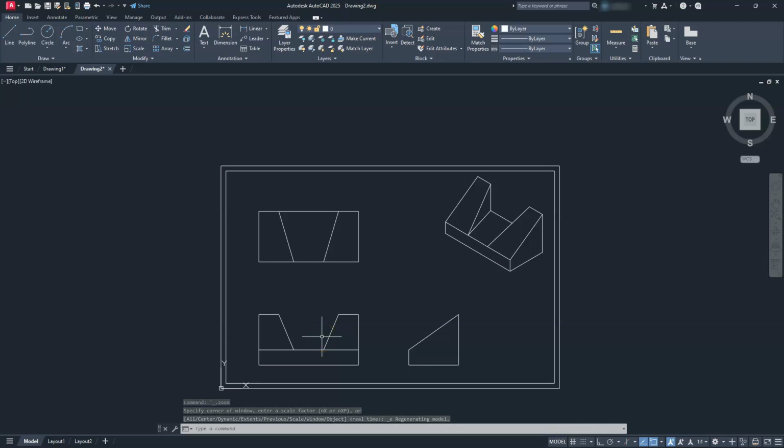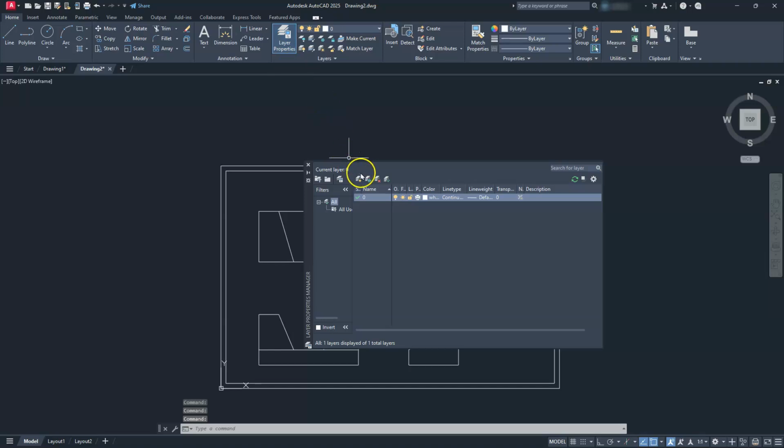I don't have any hidden lines like I said before on this one. If I really wanted to put one through here, I do have a hidden line that's actually running right through this surface here. So if we wanted to show that, we can, and I think I might go ahead and just draft it on this one because it shouldn't take us that long to do that. So let's jump to the layers property. Let's go ahead and create those two layers that we're going to use. So I have a hidden one, and then I'm going to have one that's called dimension.